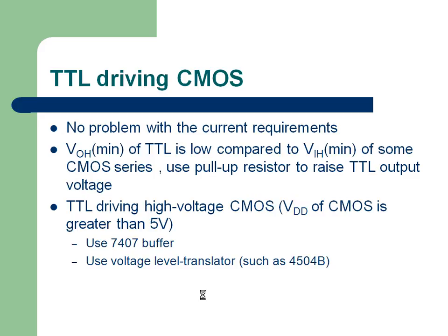This will be driving something else, right? So the driving current not only comes from this VCC but also comes from this one. So now your drive strength is going to increase. That is the purpose of the pull-up. So many times when you are taking ICs and making boards, the IC manufacturer will tell you the actual internal driving strength of this one. When you want to drive more capacitive load, add a pull-up resistor and connect it to VCC of 3.3 or 5 volts like that. That is the purpose of the pull-up resistor.